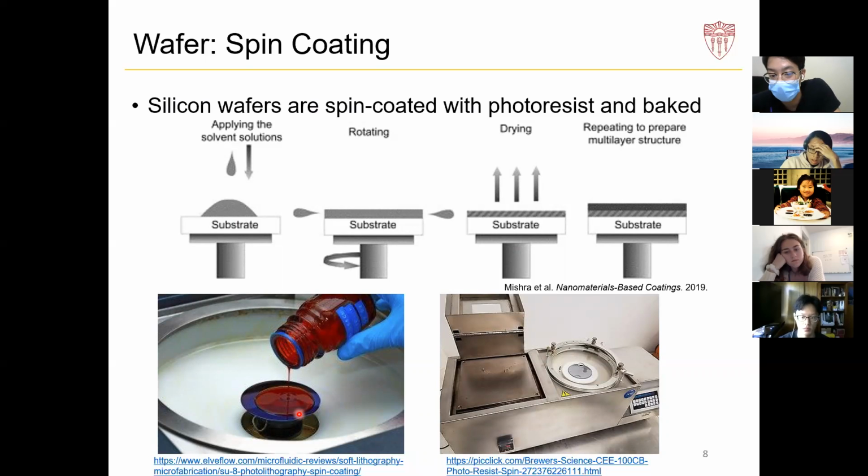Spin coating is a technique where this chuck spins around at high speeds. What that achieves in the end is that it flattens out the solution that was just deposited on top of the silicon layer. Using centrifugal forces, we make this flat, thin layer of the photoresist covering the entire surface of the silicon wafer.